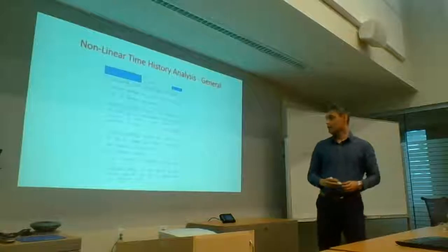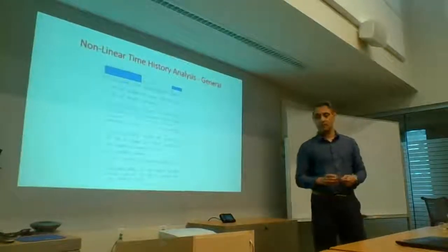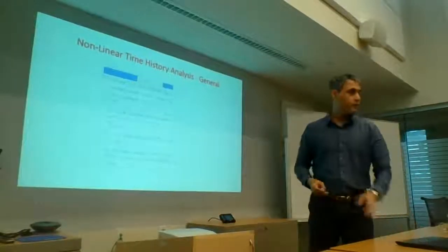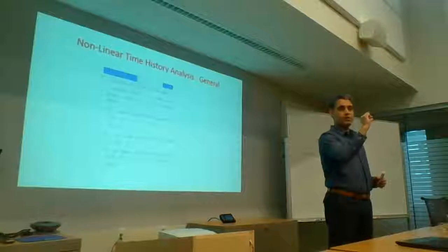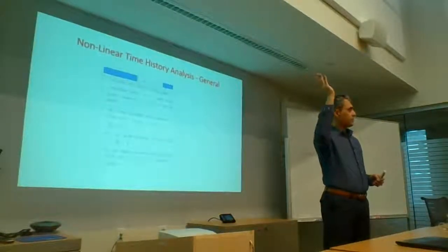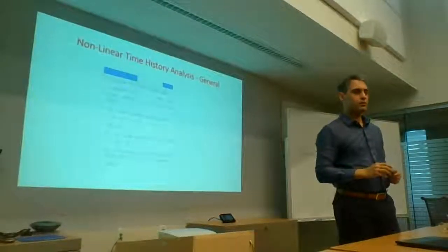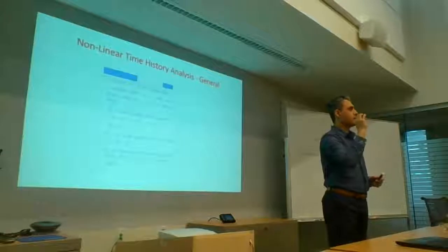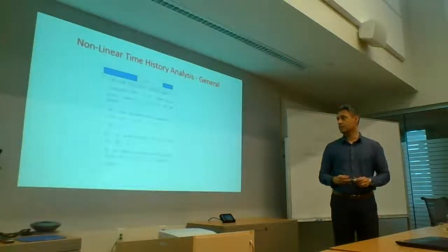The other thing I want to talk about is stability. Some of these are conditionally stable and some of these are unconditionally stable. For conditional stability, the time step has to be short enough, otherwise your solution is just going to diverge. But usually we don't have to worry about it for earthquake loading because the time step is already so small that your stability is mostly satisfied.